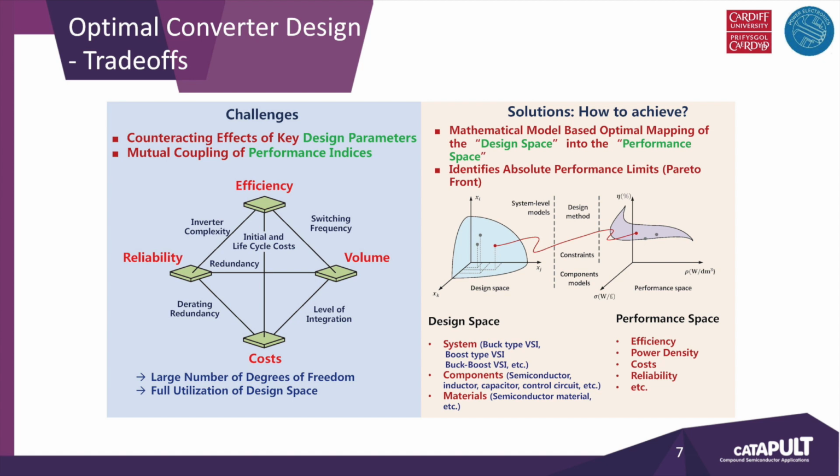So the design space I'm talking about, for example, is your topology, what kind of semiconductor you're using, and what kind of inductors you're using. So that's called the design space. And then the performance space, we are talking about, for example, your efficiency, different switching frequencies with different topologies, and how about your reliability across the life cycle of the traction inverter. So all sorts of questions.